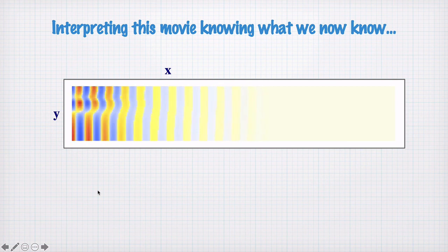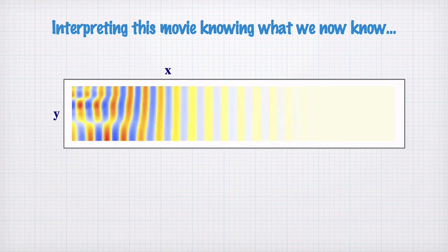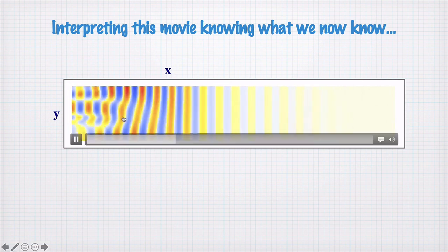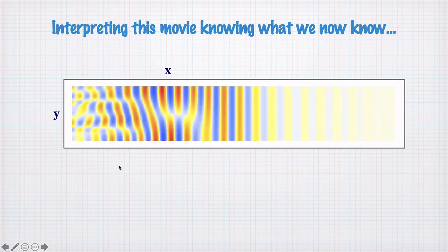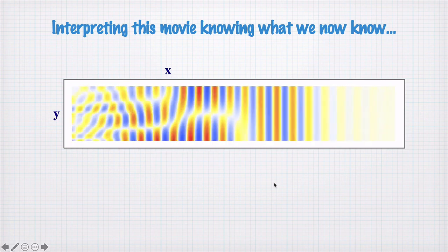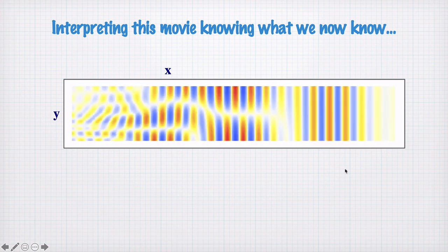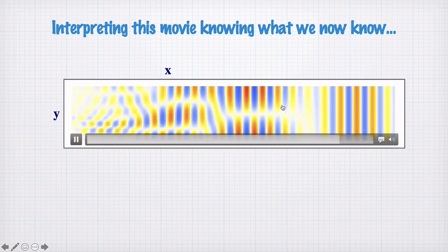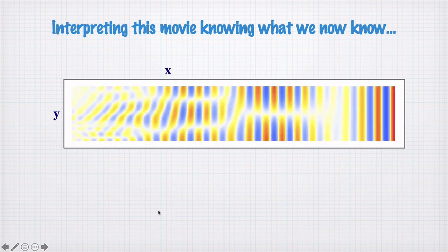And then that pressure oscillates at the frequency omega, which is the temporal frequency. And then that initial distribution of pressures launches waves with different modes, and these modes split apart as they propagate. The 0, 0 mode goes the fastest, the 0, 1, or the 1, 0 goes the next, then the 2, 0, and beyond that we have higher order modes.